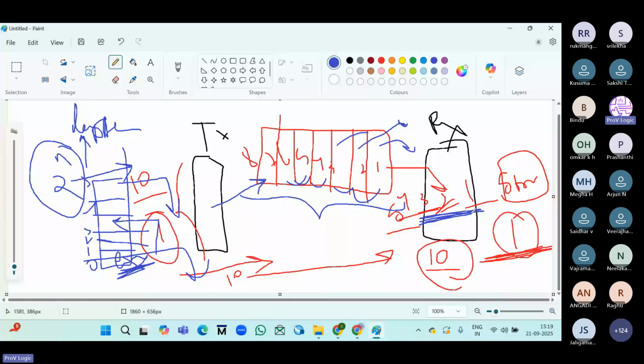So features will also be more. Whenever the features are more, automatically the speed will be high. So when the version differs, the features will be more. Like the AXI protocol has a lot of features like burst transfers, out of order transactions, overlapping. APB doesn't have those. Automatically, the frequency will be improved.